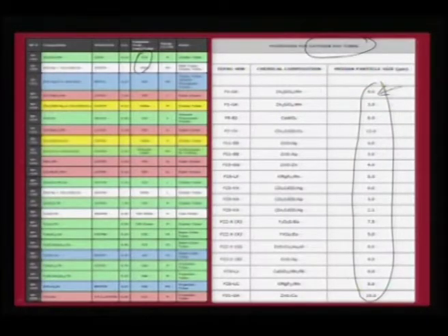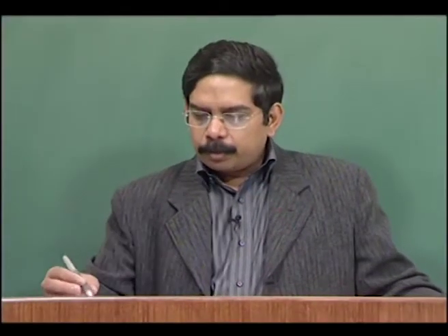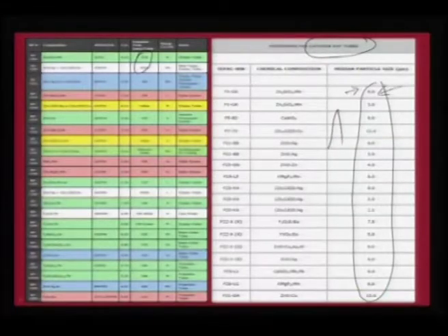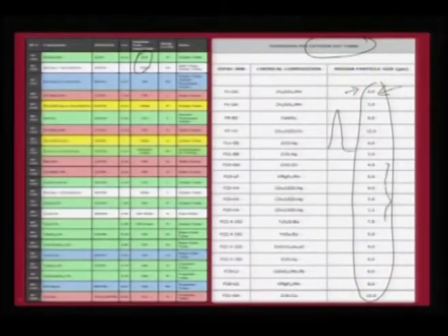For example, 525 you would anyway get when you dope manganese in zinc silicate, but you need to achieve the right micron size, and it has to be a narrow distribution. If it is a narrow distribution, then such phosphor particles can be easily engineered for making these panels. Suppose you have a very wide distribution, then it is very difficult to put that as a strand in the front panel. Therefore, one of the things that I want to point out to you is that the average size that is preferred is actually 8 micron.